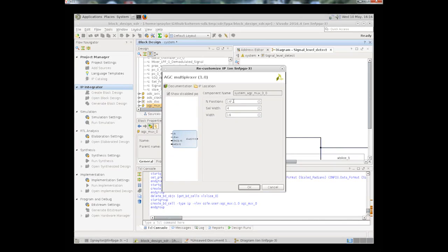value. In this case, where we've got 16 positions, it will take a 32-bit value in, and we can select to go to the output a 16-bit value from all the possible locations where you can pull 16 continuous bits, either from, if you imagine the 32 bits in a line, you can choose 16 bits of those either from the left hand side, the most significant bits, or slide along towards the middle or towards the right hand side. In fact actually 17 positions, but let's not quibble over that. We'll put 16, we'll use a select width of 4 to be able to address all those different positions.